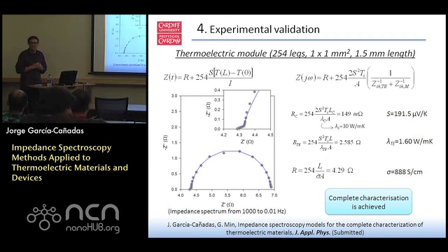I'm asking this because you said that you would apply a voltage like 10 millivolts. If it's a p-n junction, you need the linearity, but you also need to get the device on. But I guess the reply was that you can apply a DC and on top of it apply a small signal, so you can make it on. But what you're measuring is the variation on top of that. You don't measure the DC.